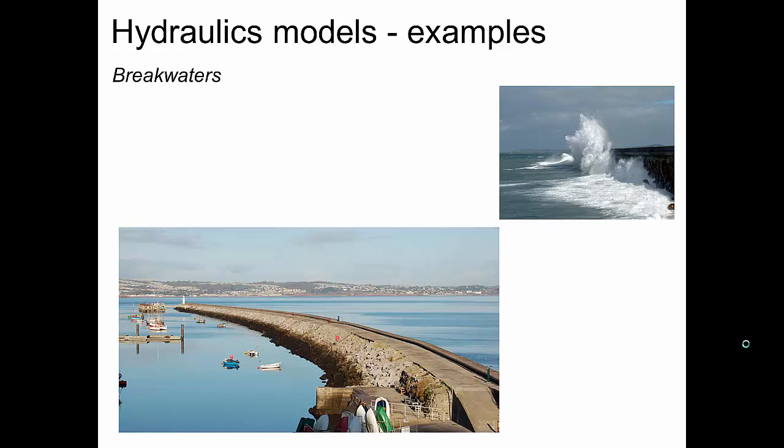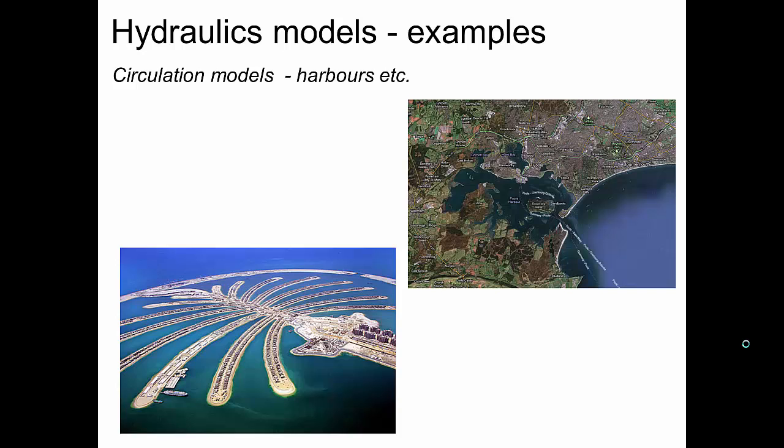So we can test very, very quickly over a range of sea states the integrity of these structures. So experimental testing is very useful, and obviously we'd have to scale then the wave height, frequency, different types of spectra, so different groups of different types of waves we could fire at the breakwater. So all that could be scaled down, and then we'd geometrically scale the breakwater down. And then what we would scale back up again is the forces acting on the structure. So we do testing of a small model in a wave basin and then scale that up to a full 100-meter breakwater that's 6 meters high, for example.